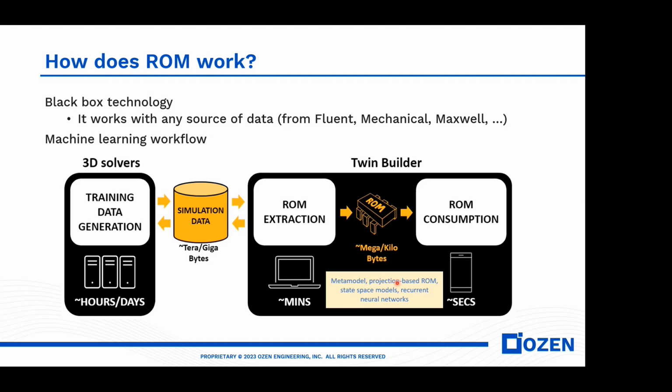If you increase the number of modes by too much, your reduced order model will become bulky. So there is always a very balanced point which needs to be found, and that is effectively done based on the validation of the reduced order model against a calculated solution. So we will take a look at that at a later point.